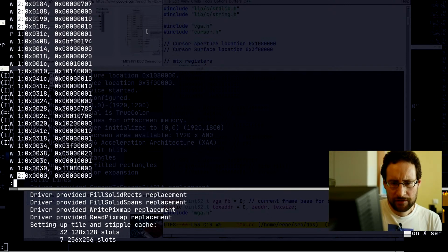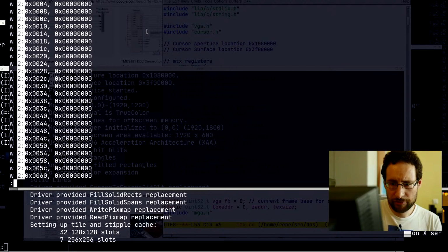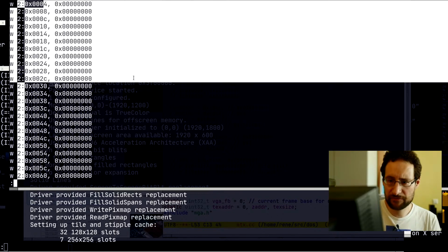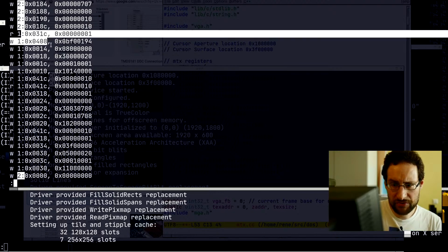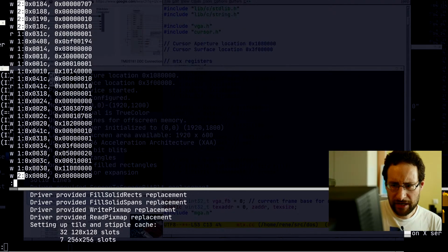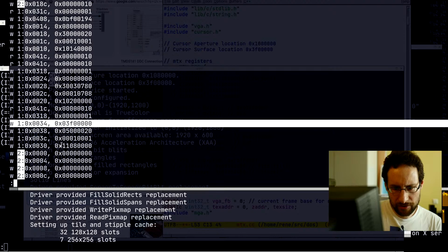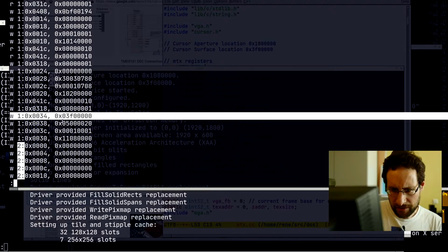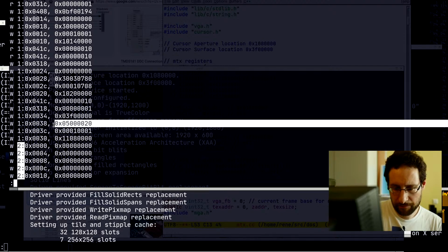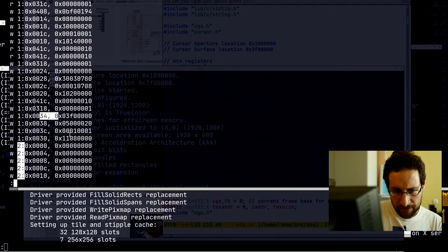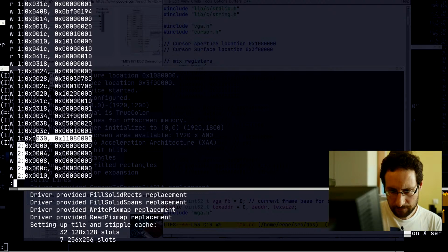Because then it's resetting this, as I said already before, and this is a frame buffer write of filling this with black. As you see, this is the second file descriptor for the VRAM, all black. So this here is the cursor aperture as we determined already, and this is some control bits, maybe like format, like bit depths or whatever that belong to that, I guess. And again, this is a physically, as a virtually mapped thing for the cursor.